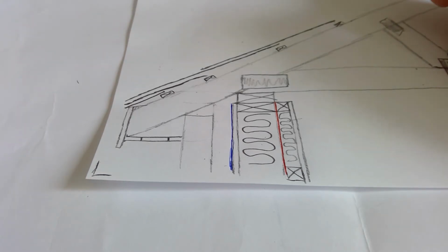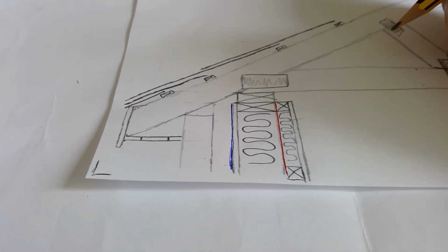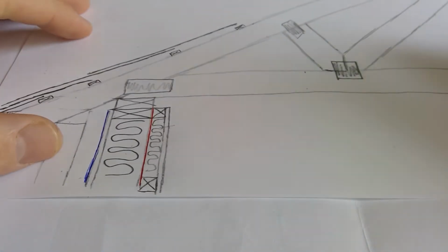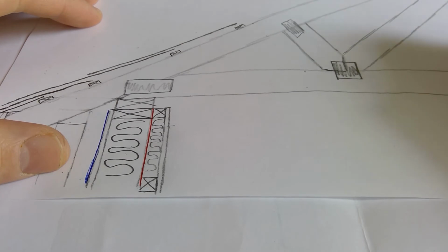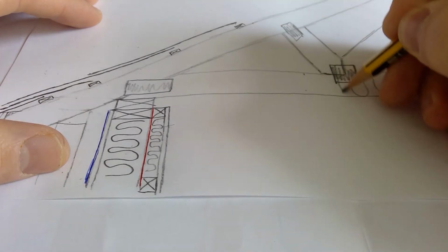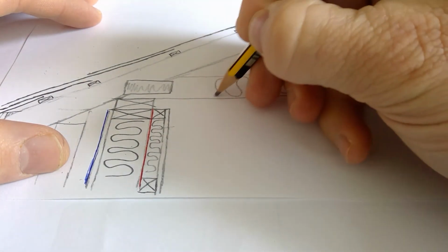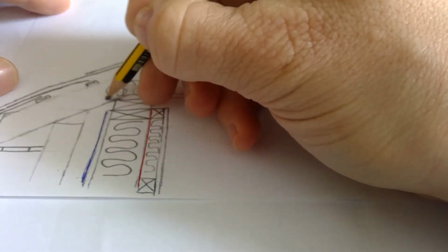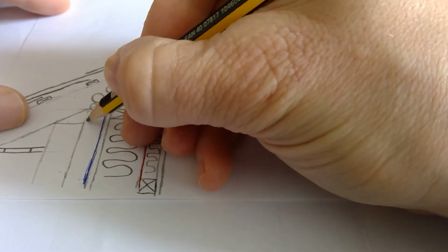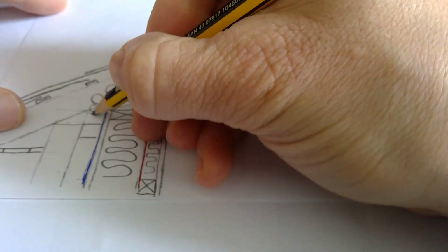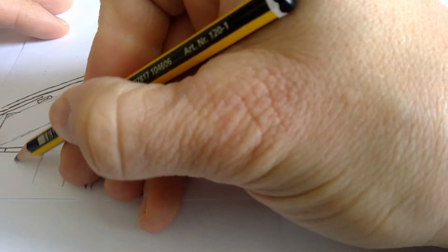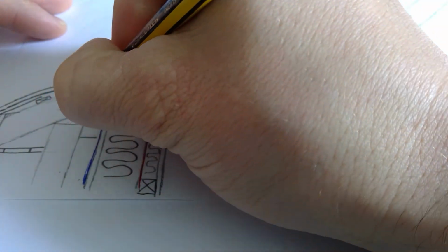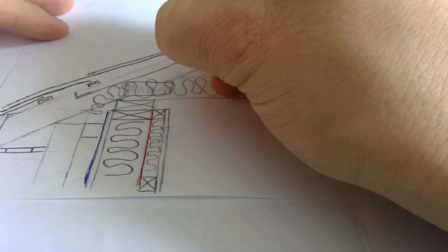Okay, that's the slates. The ventilation, it asks specifically for, there's insulation, by the way, is going to be all the way along here. I'll just do that quick enough. That'll go and that'll run in here. There'll be a cavity closer on top of that, which I've left out also. Now the ventilation can sometimes get blocked by this insulation, so we put our eaves ventilator in there. We've looked at that several times last year. Eaves ventilator into position there.